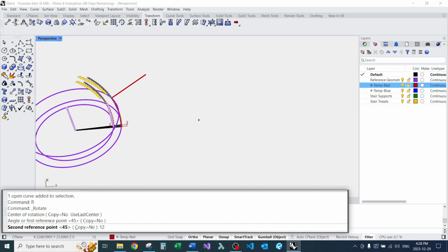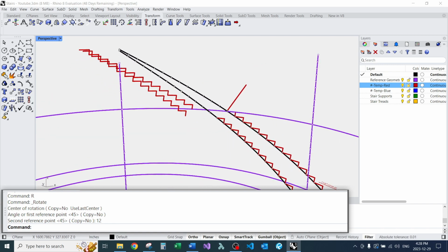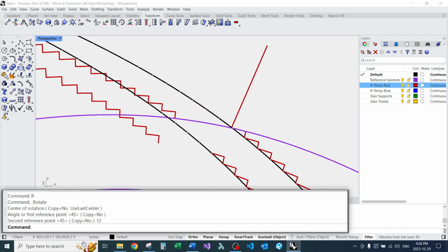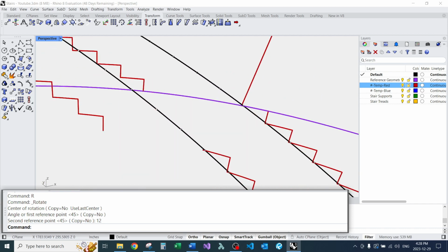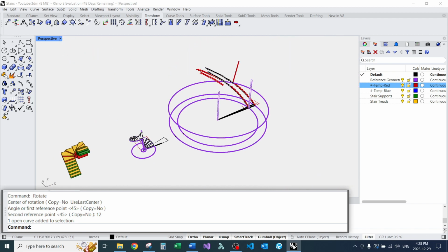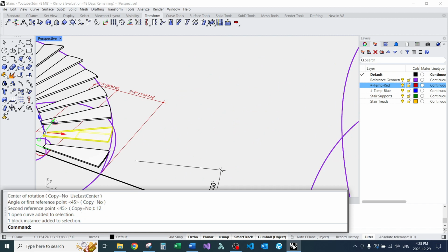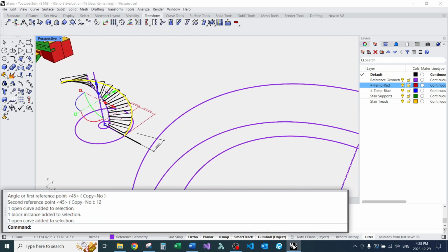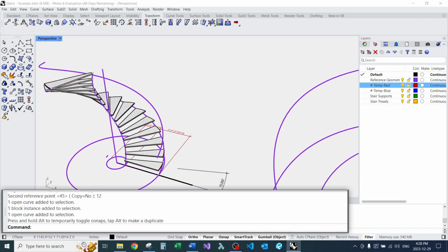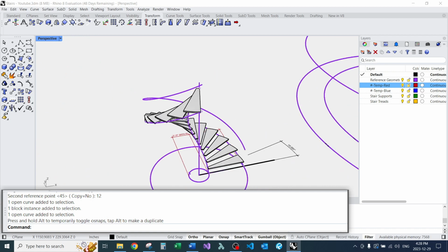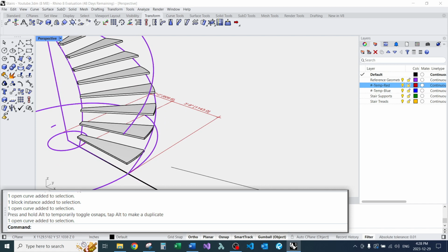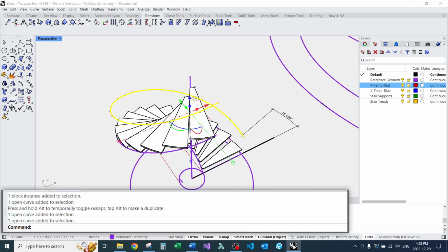Let's say 12. I'll go with that. So depending on what you're doing, like if you're doing handrails or something, it would be prudent to also maybe split these helixes, because you'll use these helixes, that's why you want to save them. You're going to use them not only for laying out your stair treads, but potentially also for sweeping your handrails, maybe arraying the handrail posts along the curve, stuff like that, right? You want to keep these.